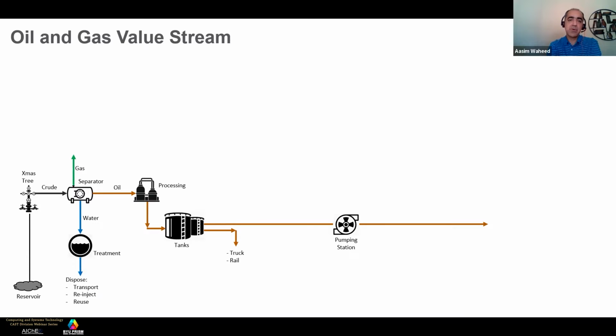And given the profile of the pipeline, which is to say how high or low it goes as the profile of the land changes, it could be about 20, on average, 25 miles. Every 25 miles, we need a pumping station. If it's hilly, of course, we need more pumping. If it's flatter, then less pumping. But 25 miles, and the next pumping station will come up.